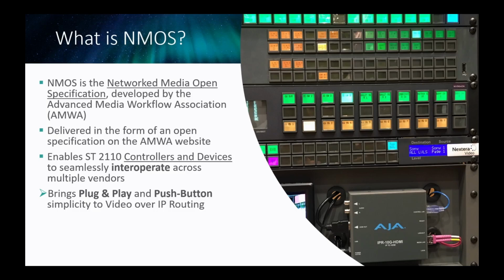Okay, so what is NMOS? Well, it's yet another acronym. It stands for Networked Media Open Specification. It was developed by the AMWA Group, Advanced Media Workflow Association, to try to come up with a set of guidelines for control for IP-based video systems. So you may recall in the SDI world, every SDI router had their own control system. They're all incompatible with each other. So every system had to make special drivers for everything. We didn't want to do that in IP. We said, even though you might have 100 vendors doing IP systems that are all 2110, let's make sure it's all the same control system, so you can mix and match between the vendors.